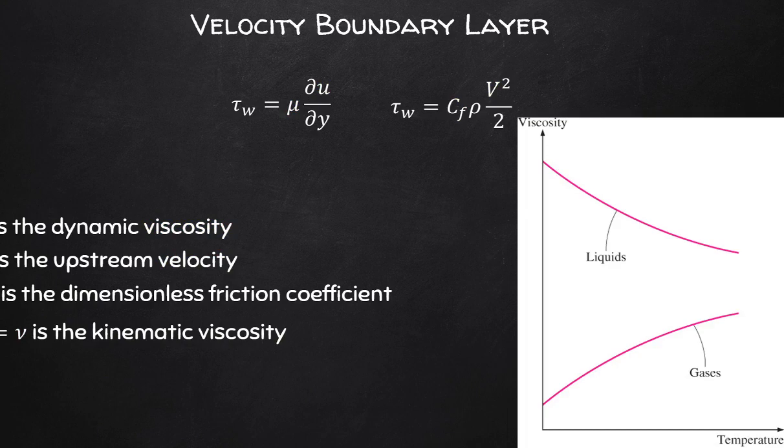Realize how increases to the temperature will affect the viscosity of liquids as well as for gases. Look what happens. This might influence frictional losses, for instance, because frictional losses and viscosity are related by the equations as shown. So also notice how the liquid viscosity approaches that of the gases with increases to temperature. So if I increase the temperature of the liquid, I'll tend to have less frictional losses, for example.